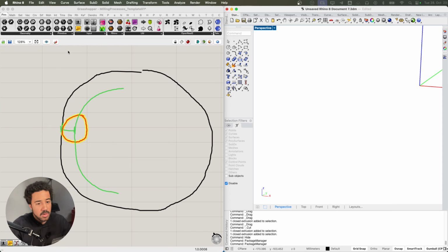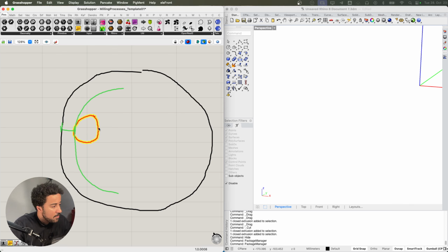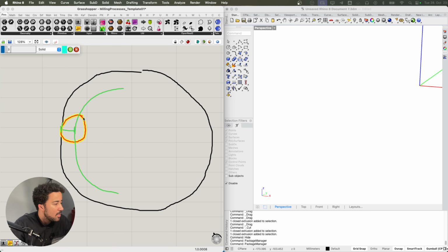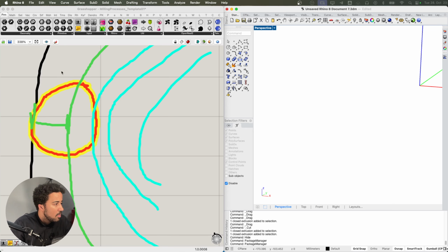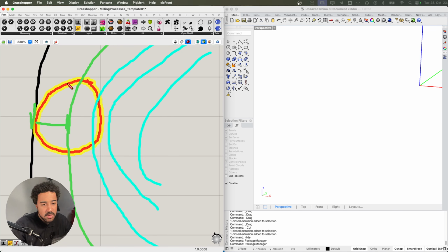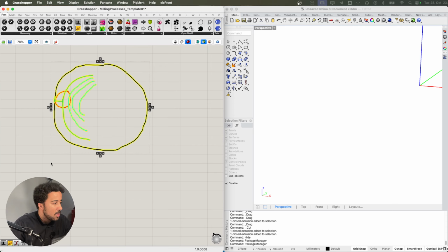Now, depending on what you're cutting, you can also just continue using this offset and basically offset the cutter by half of its diameter every time we go further inwards. But sometimes it's also good to have multiple steps that are smaller. So some steps that are just slightly smaller, maybe a quarter of a diameter, and to change the distance that we are going inwards at each step, just to make sure that we're not taking too much material and the cutter can actually keep up with the amount of material that we want to remove. I hope this makes sense.